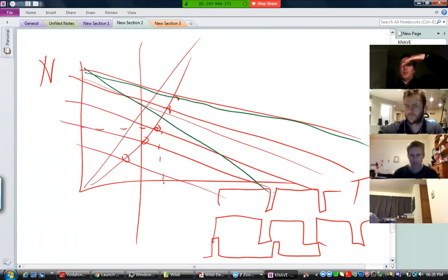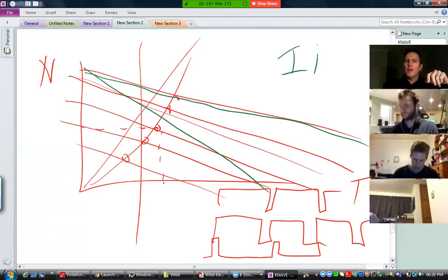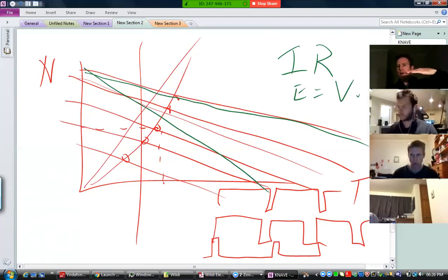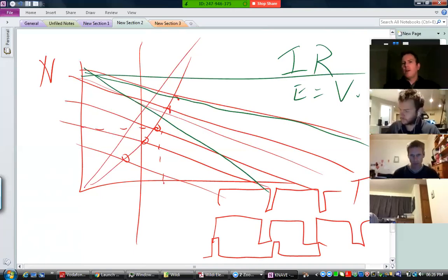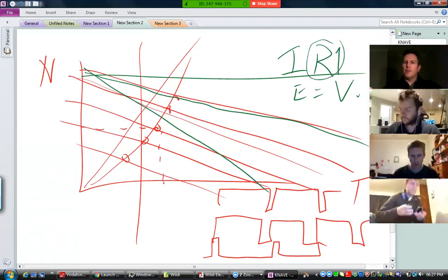Remember, the more perfect the armature was, if it had almost no internal resistance, then we end up with no IR drop across the armature. In that case, the back EMF would equal the supply voltage, and the thing would actually have a straight, horizontal graph. The speed would never change. But if we have a real resistance, we get a bit of a slope going. If you increase that value of resistance, then the slope becomes steeper.